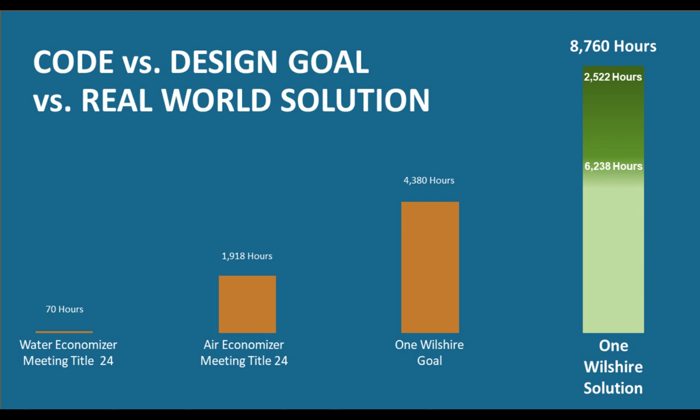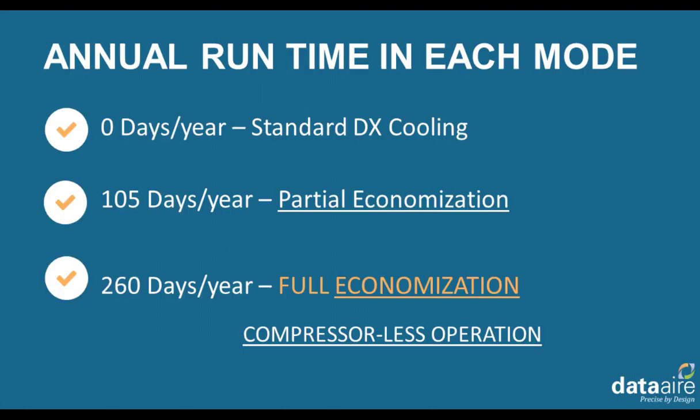The other hours above that, the 25, 22, that's additional hours where we were able to do partial cooling in that compressor assist mode. So that's just an additional benefit on top of what the original requirement was. So the outcome was there were 3 modes of operation, like I mentioned, but this design in the end only really needed 2 modes as they were able to maintain the high side of the water at 74 or less. You would never need to go into that full DX mode.